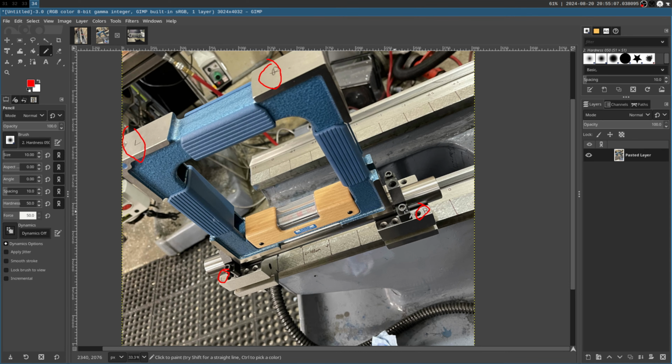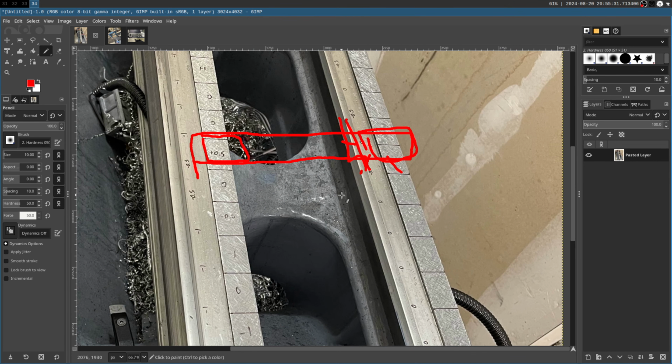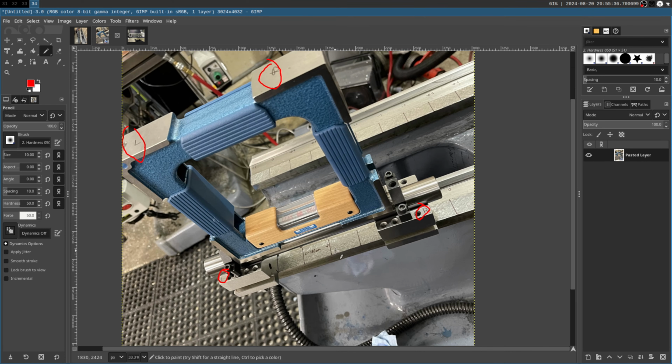But in reality, we're factoring out one of the largest errors that could happen, which is a difference between these two blocks in their entirety. Really, the variance we're going to have is just where we set this on this round bar, which is effectively none. I can go through and repeat the measurements that I'm taking over and over and over again. And that's typically what I'll do: I will take a whole set of measurements and then randomly pick out some points to remeasure to make sure that they match the measurements that I took.